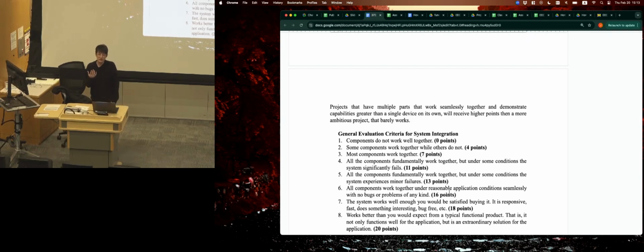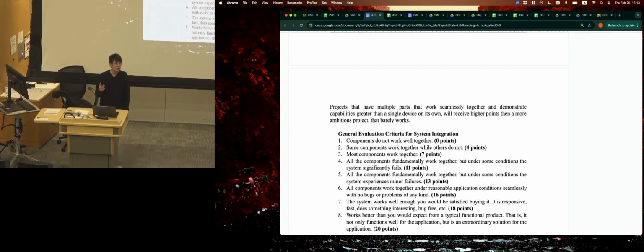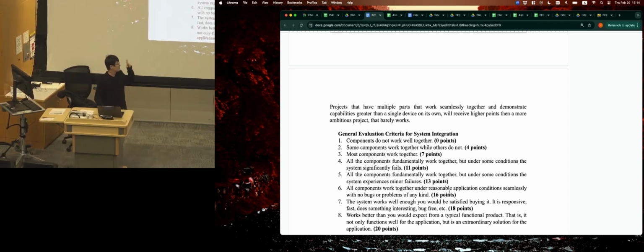It's one thing that you have each of the individual components working on its own, but you'll be surprised how much work and time is needed to bring all those components together, especially when you have, say, 5 or 6 components, because chances are they might interrupt each other and influence each other's working during the integration, or they just mess up the order, etc. So it actually takes more time than you would think most of the time. So make sure you start thinking about how to integrate them together at a relatively early stage.